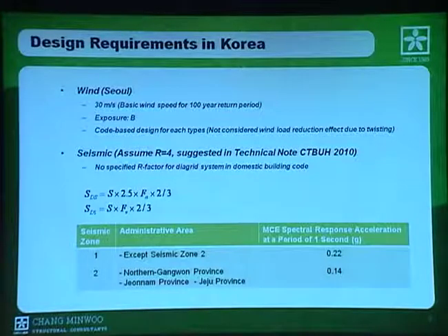And for the seismic load, an R factor of 4 was used for the system. And this R value was suggested by SOM in the technical note of CTBUH 2010. And because Seoul belongs to seismic zone 1 in this table, 0.22g was used for the calculation of MCE spectral response acceleration at a period of 1 second.